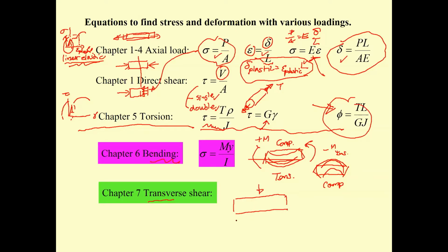And then later, not only this one, the concrete also has the transverse shear under the application of a force like this. The shear will cause the crack like this. The moment will cause the crack like this. So for the moment you put the reinforcement here, to help the structure resist the crack. How about the inclined crack like that? What are you going to do? You're going to put the stirrup. The stirrup is the steel in the vertical direction. So for the reinforcement to resist the shear, we put the stirrup over here to prevent the crack like this. Also, you have to put it on both sides to prevent the crack. This is a small example.